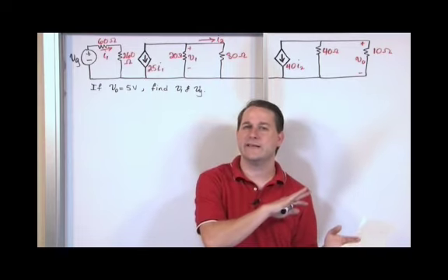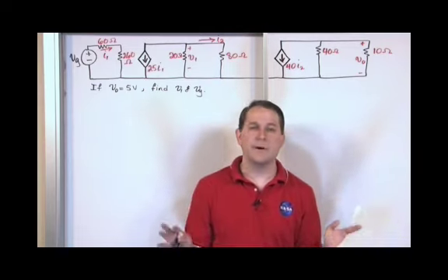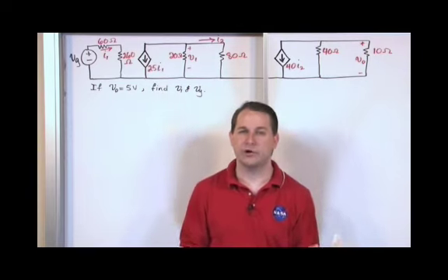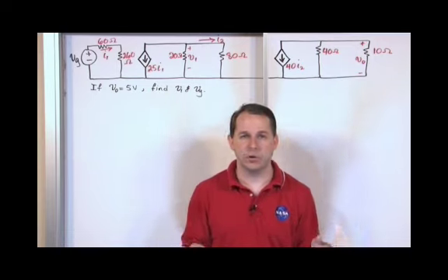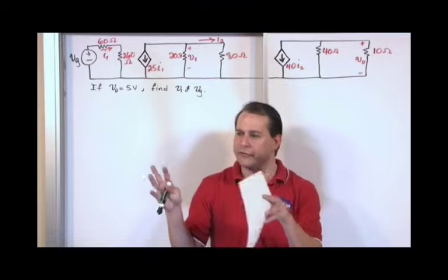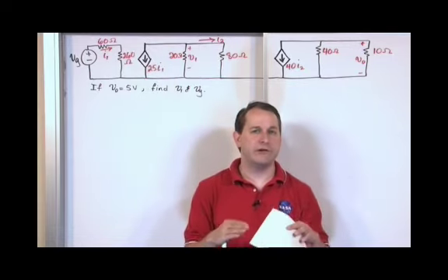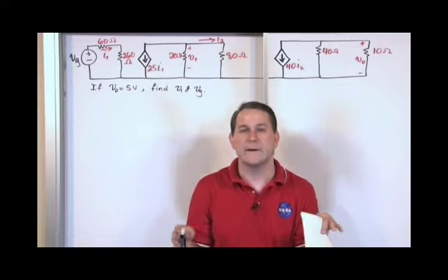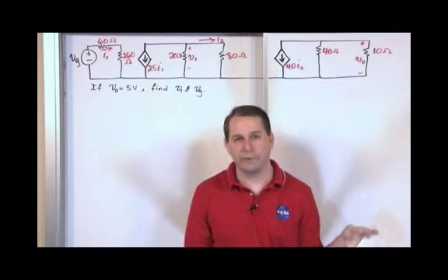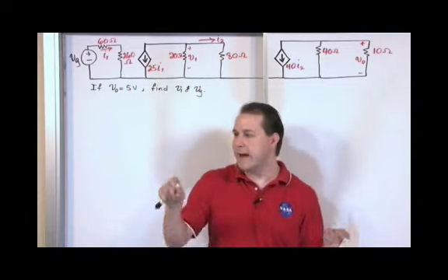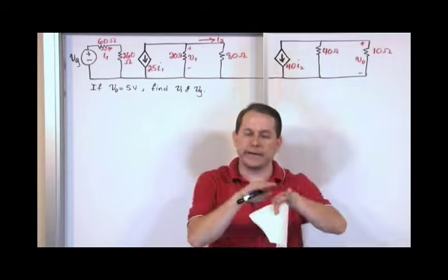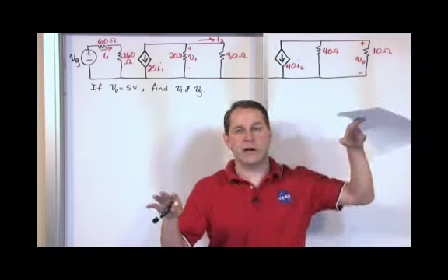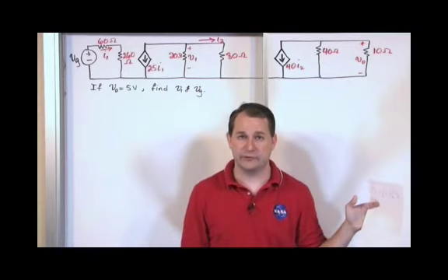We're going to get into this idea a lot more. But the bottom line, the thing to pull away from it, is the best practice when you build circuits that are commingled, co-located, part of the same system, but they're separate circuits, right? You really need to make sure that their voltage level for the base, the low voltage of their sources really, are all at the same potential, all 0 volts. So that when you have a battery here and a battery there and a source here and a source there, all of their 0 potentials are in the same place, so that they're all playing nicely and nobody's floating up and nobody's floating down, creating these dangerous potential differences between each other.